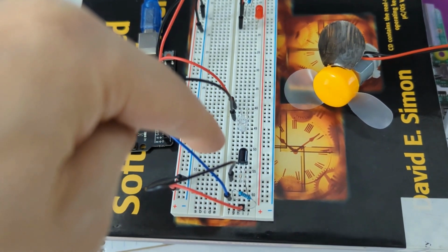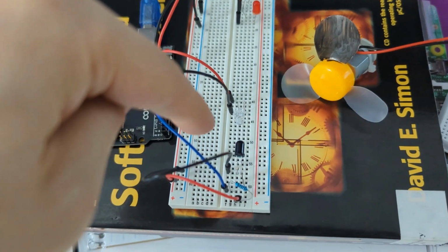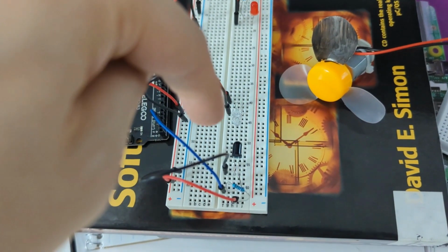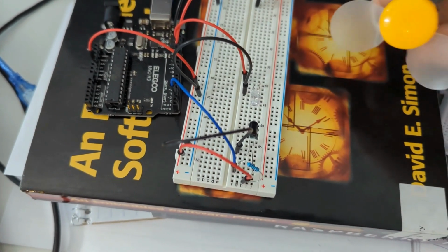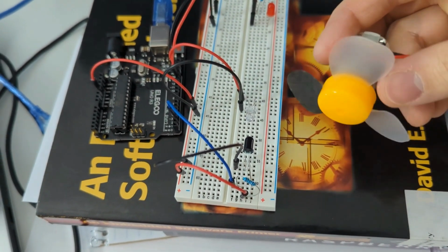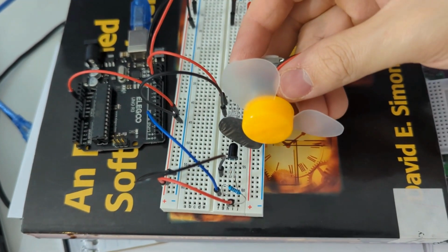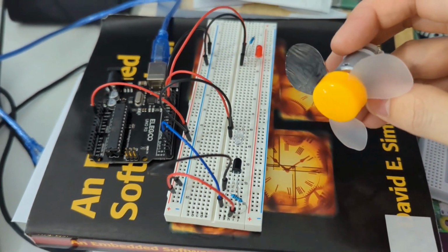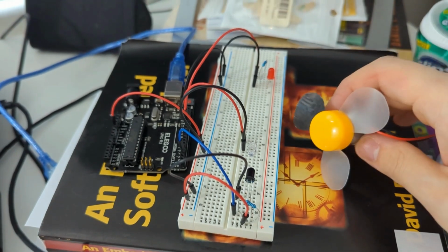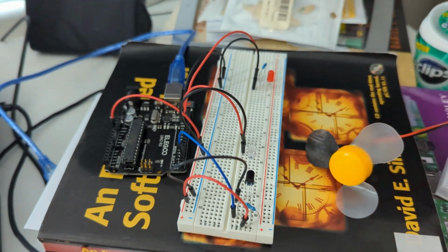The black looking LED is actually that photodiode, and you can see just about a half inch of space between them. Not very much. I had to make sure that they were pointed to one another and very close by, so I could actually break the beam with this propeller blade when it passes through the middle there. So you'll see that status LED go. I won't go through the nitty-gritty of the circuitry because I've already done that in the previous section of the video, but let's go ahead and get started.